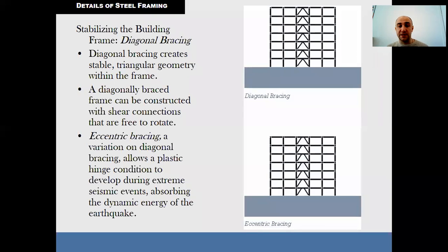Vertical bracing between column lines in vertical planes provides a load path for the transfer of horizontal forces to ground level. Frame buildings require at least three planes of vertical bracing to brace both directions in plan and resist torsion about the vertical axis.